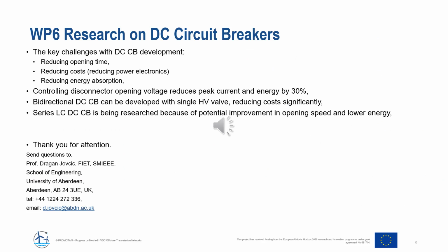As the conclusion, we can say that the key challenges with the future DC circuit breaker development are reducing opening time, reducing costs, and reducing energy dissipation. 3 different research approaches on improving DC circuit breaker have been shown. Controlling disconnector opening voltage is shown to reduce the peak current and energy by approximately 30%.